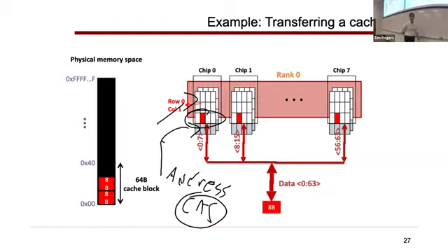Other questions? Yeah. When you end up loading a row, does it actually load all of the banks of the same chip for that given row, and then it just switches between each of those banks? No, it's initiated on a particular bank. Let me think about this. Every bank will have its own sense amps associated with it.